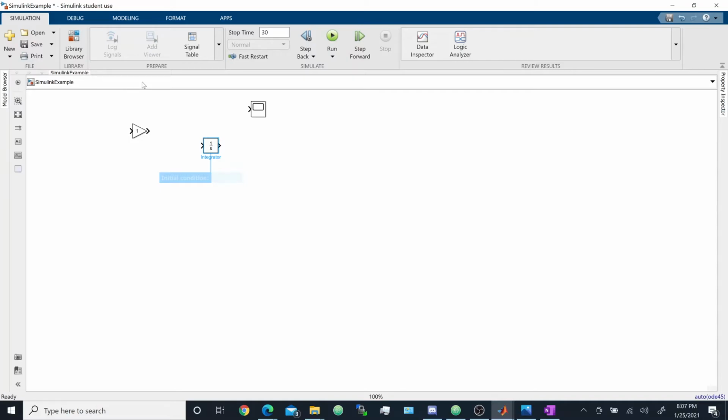All right, so let's take a look at our picture again. We're gonna have x of s, and then we're gonna have a 1 over s. I'm gonna format it just like this. We're not gonna need all these summations though, I think, because only right here is the one spot that it sums two different signals. So let's go ahead and get started. First thing I'm gonna do is if you double click on these objects, it'll give you the full parameters for it. So you could go and click, okay, so 1 over 2 is our gain.